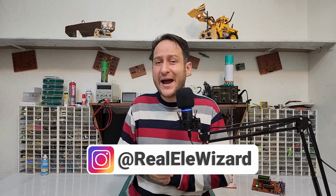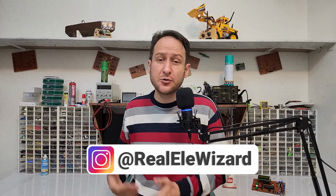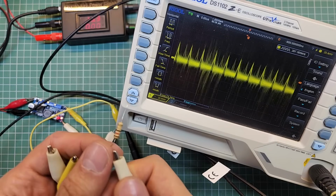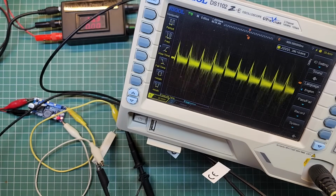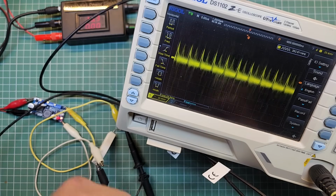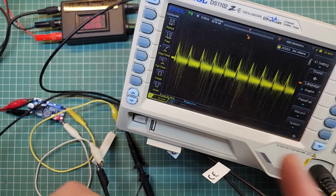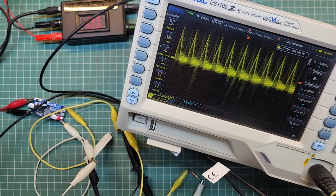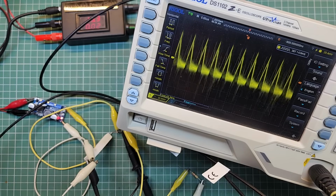But what if I add some more load at the output to draw more energy from the output and empty the capacitor faster? In that case, these pulses have to increase, right? I'm counting down the seconds until I test it. Now, if I add more load at the output, we can see that these tiny sawtooth-shaped pulses will grow, and if I add even more and more load at the output, they will grow even more. Look. Now you can see that the amplitude of those tiny sawtooth-shaped pulses has increased.